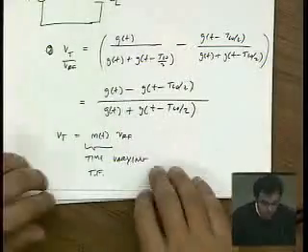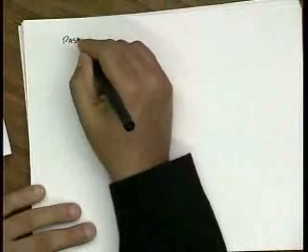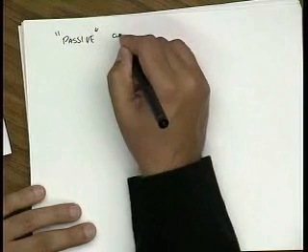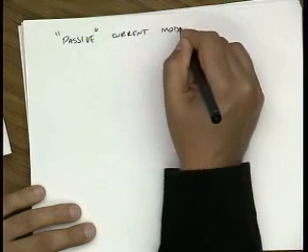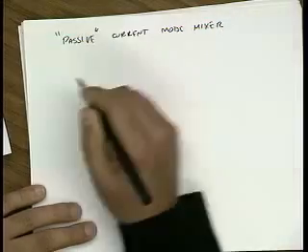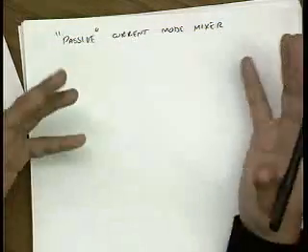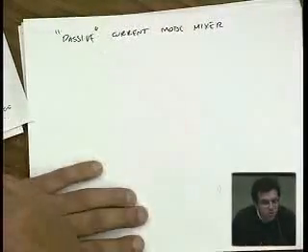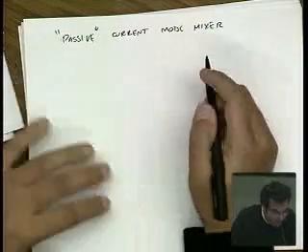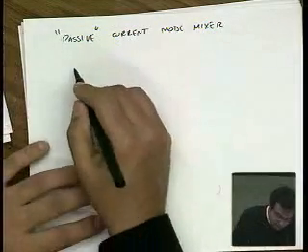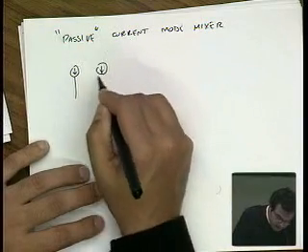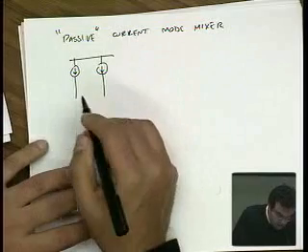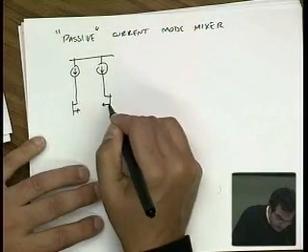Okay. Well, this one is kind of a passive mixer, but it's a very related beast. So let's call it, for lack of better name, a passive current mode mixer. Okay? You might object and say we already studied a passive current mode mixer. The Gilbert cell, if you take the transconductance cell away, is also more or less just a current commutating mixer, right? But what we're going to do is we're going to take almost the same exact circuit and basically run no DC current through our Gilbert cell, or let's say our Gilbert quad.